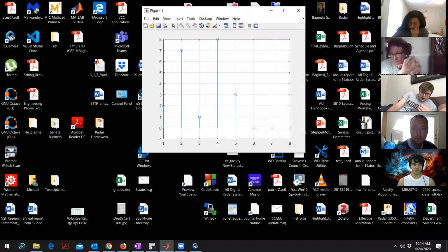I can tell you this. If I give you the pole-zero constellation of a function, H of z, and I give you the scaled magnitude, you can assemble a function that would be H of z. Do you agree with me? Yes. All right, now if you have that function, if any of those poles or zeros are outside the circle magnitude of z equal 1, then it is unstable, and you may not be able to do inverse convolution. That's the thing with phase minimum, you can.